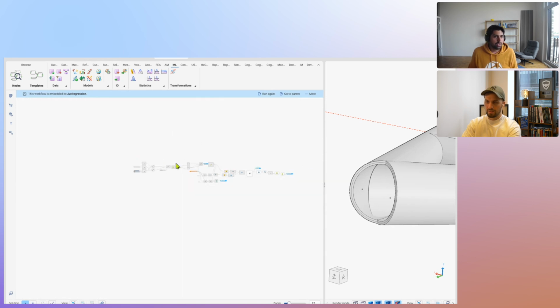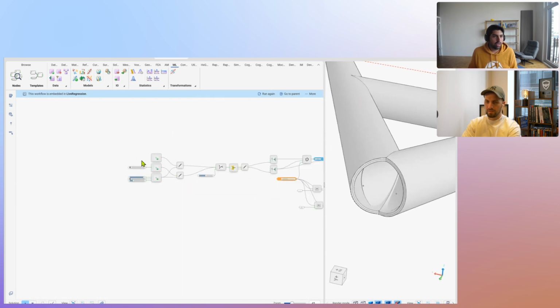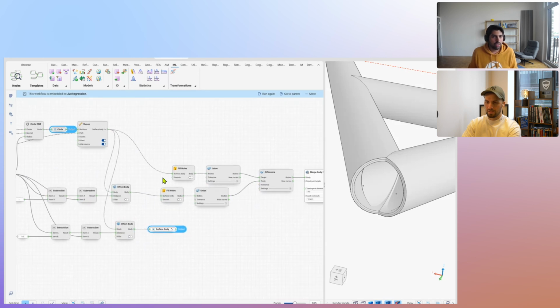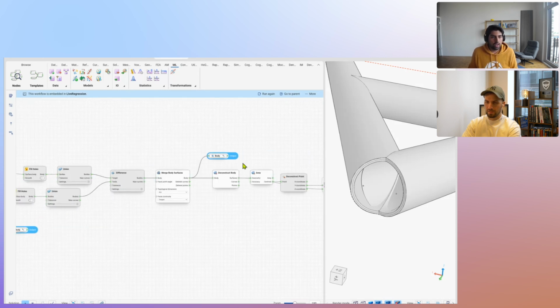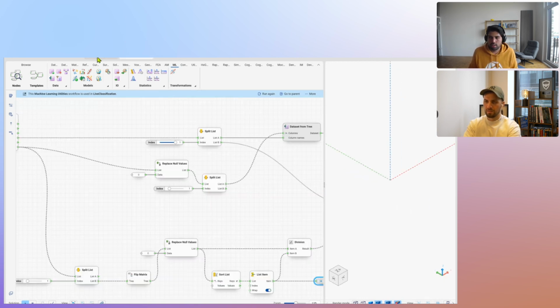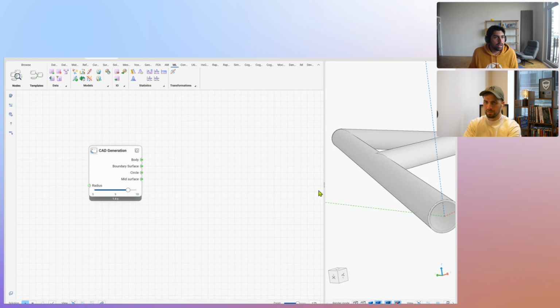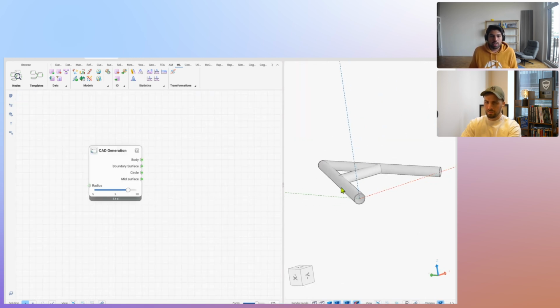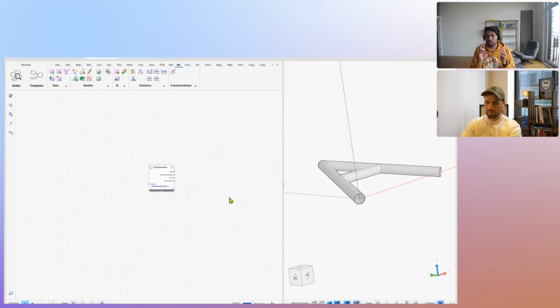And how it works in the background is I have this logic to create this CAD geometry based on some parametric values. This whole CAD geometry is basically constructed entirely in Synera. And my problem definition is going to be simple. I'm just going to constrain one side, apply forces on the other side, and measure stress, displacement, and maybe, I guess, mass. And then we see how we can do regression tasks inside Synera.